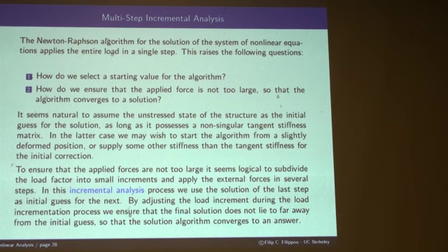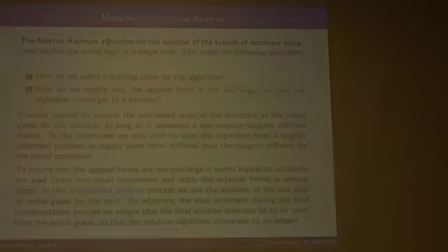Get to know your structure, right? I hope nobody in here is going to attempt to run a nonlinear analysis without having run a linear analysis first on a structure. Now I understand that some software out there discourages you from doing that because they have different inputs for linear versus nonlinear, and you cannot use the same things.